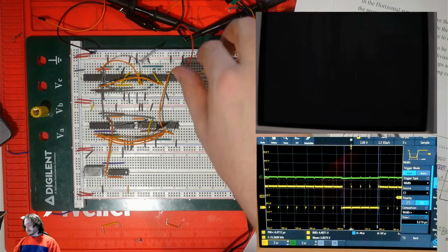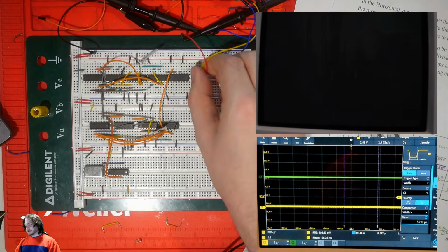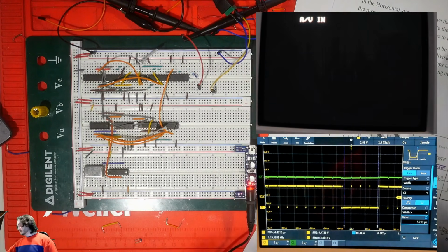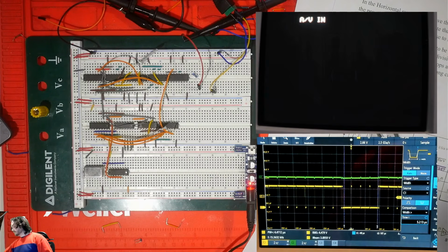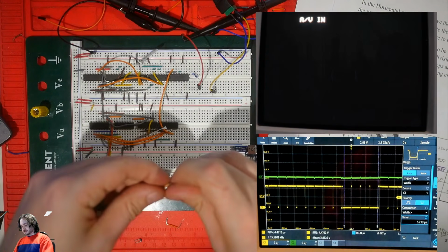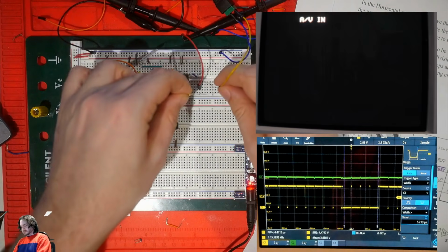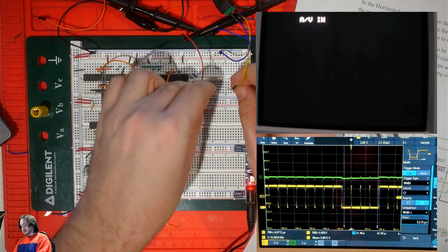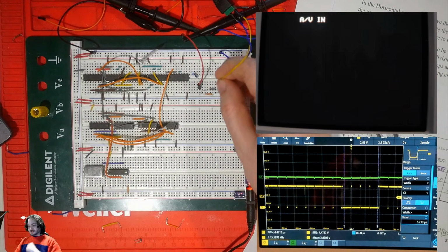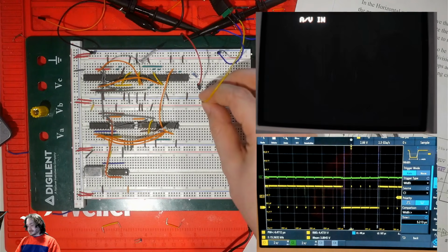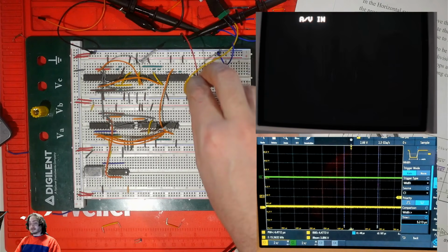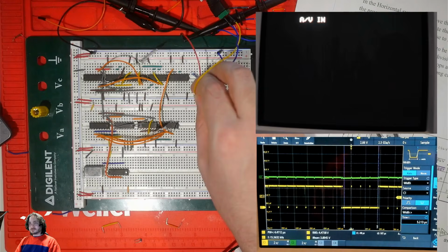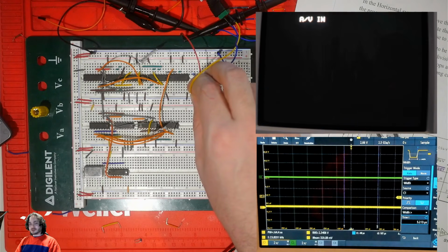But we can try moving around these connections, add another resistor. What I'm doing now is to create between these two resistors a place for the oscilloscope lead, because when I connect the video to that directly, it's going to pull that, so that goes away from the oscilloscope, but it just goes to the TV.